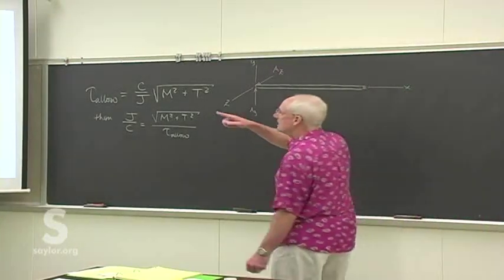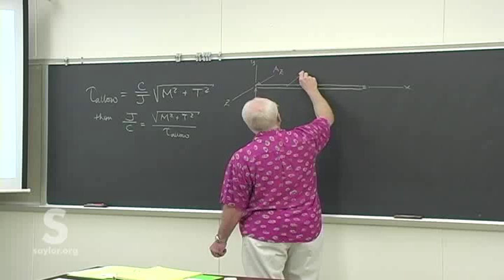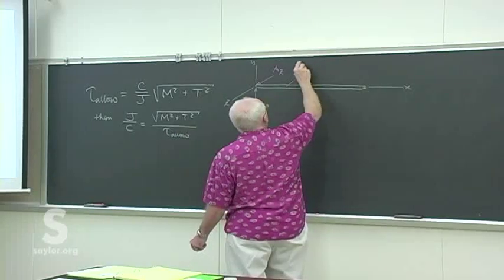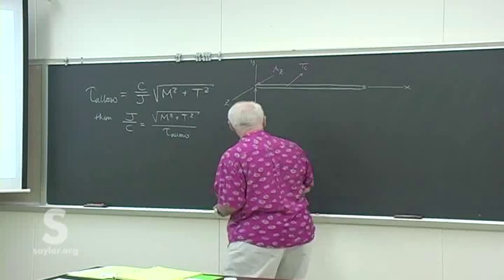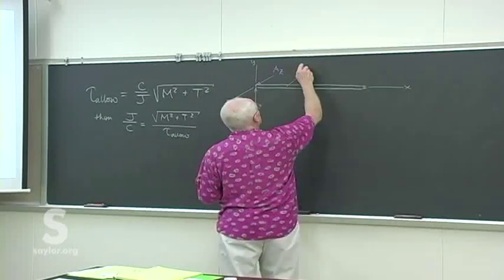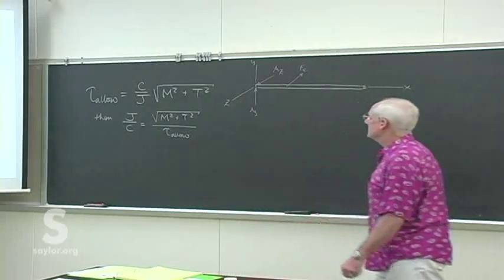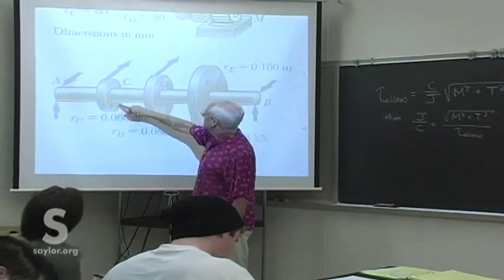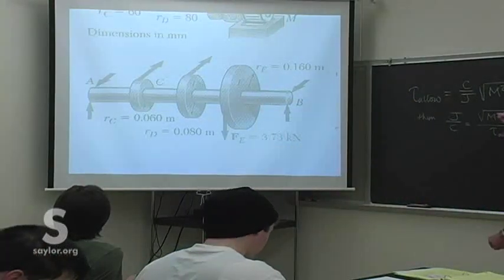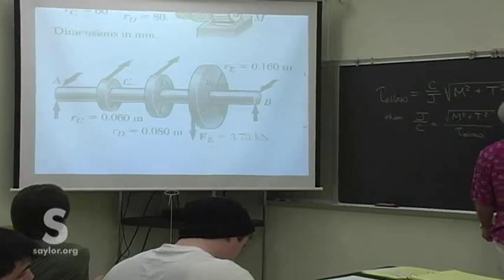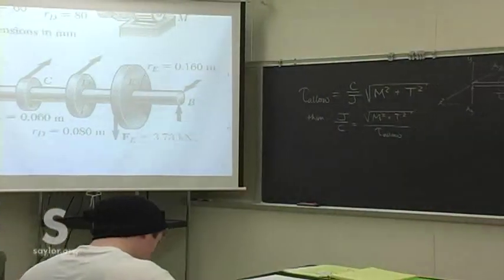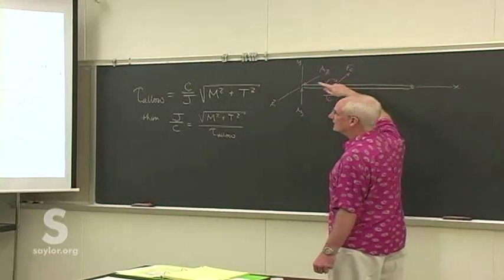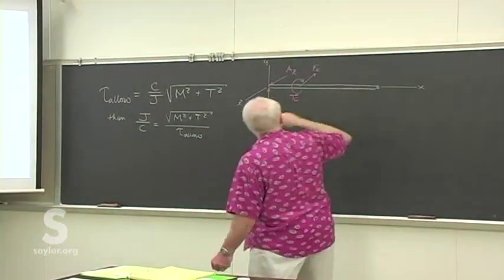Then at gear C, we have a force applied in the Z direction. I guess we'll call that, let me keep my notes the same, no, this would be F_T, I've got for torsion. So we call this the force at gear C. But because gear C has a radius of 60 millimeters, there's going to cause a torsion there, and it will be in the minus X direction. So we'll draw it in so it looks something like that. And it's fairly easy to figure out what those are equal to when we get the rest of the details in here.